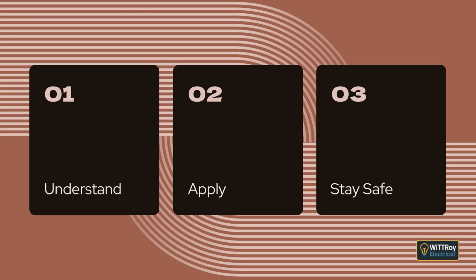Clause 3.11.4.6. This clause is about making sure we always know where underground cables are, so they don't get damaged when someone digs. First, we must put a marker sign showing where the cable goes into the ground or comes out near a building. If this point is already very clear, then a sign is not needed.